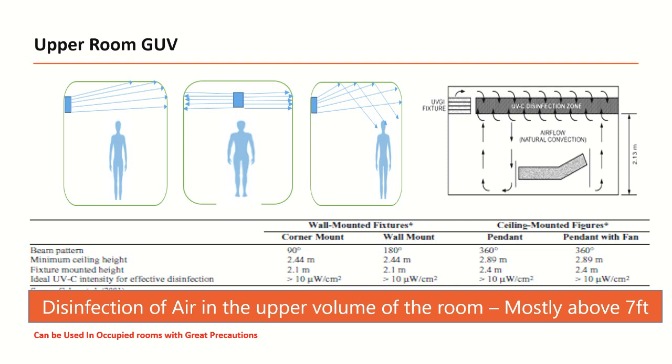Here, normally two types of luminaires are used. One is the open luminaires, and one is the luminaires with louvers. The luminaires with louvers give a very narrow band of radiation. So it is very useful in controlling the beam of the luminaire. But the efficiency of these louvered luminaires is very low, around 30% of the open luminaires.